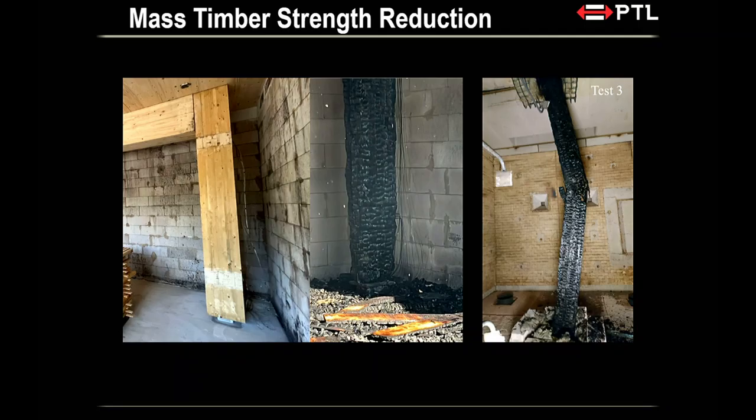So it's extremely hot at that particular region, right? And with fresh air coming in, if you have a lot of char already developing, that fresh air just helps oxidize the char. When char gets oxidized, it turns into ash. It just flakes off, right? So this is what the researchers suspect happened to cause this column to be a bit tapered, right?